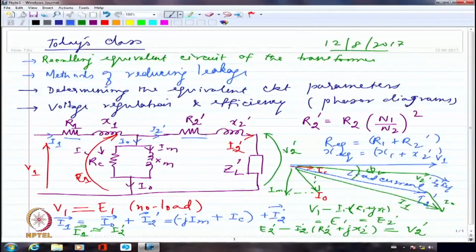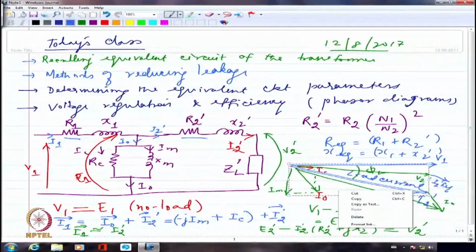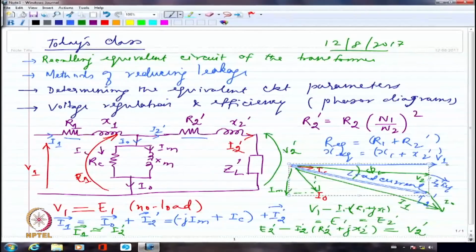That I am going to multiply by the resistance. And after all, the current multiplied by resistance will be in phase with the current itself. Right? So, I have taken this in phase with this. These two are in phase. And to this, I have to actually draw a perpendicular. So, I have to take it like this. If I drop a perpendicular, that perpendicular is indicating that the resistance drop and inductance drop will be at right angles to each other. I hope you understand.